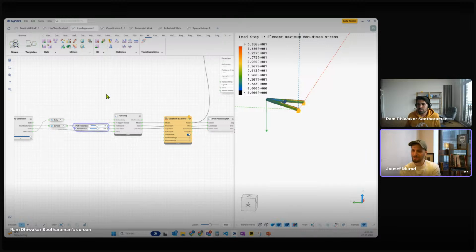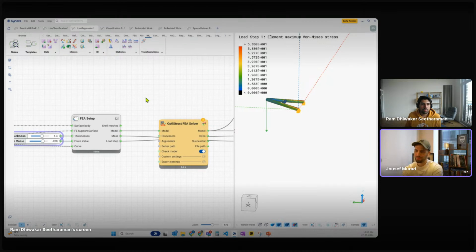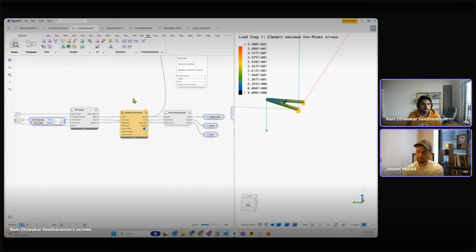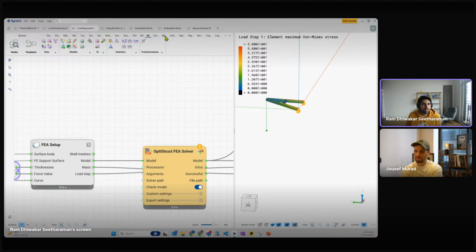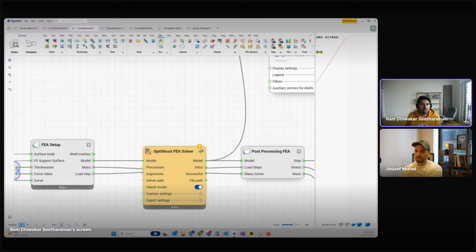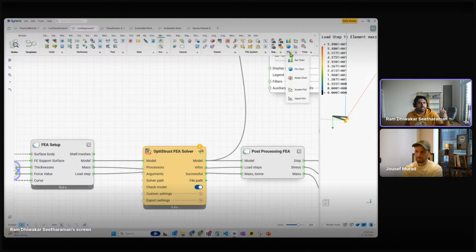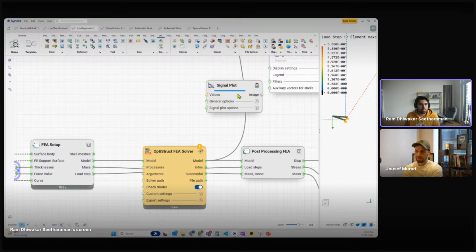But I think it also is cool in Synera because you would be able to run a number of experiments inside of Synera and then plot the degrees of freedom and the stress. Exactly. You can also have your own plotting functionality. So you can write a custom sensitivity analysis logic, and then build a plot of some values, how they were spread, how the values varied, and you can find the ideal element size for you.